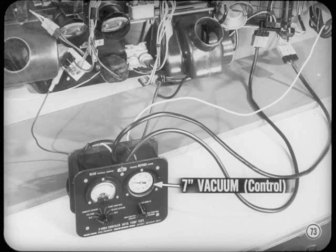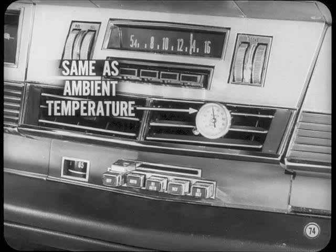Disconnect the wires from the compressor clutch and run the engine at curb idle speed. Place a thermometer in the right center air conditioning outlet, push the auto button, and set the tester vacuum dial so the tester vacuum gauge reads 7 inches. This is the control vacuum supply to the water valve thermostat. When the thermometer in the outlet settles down, it should read the same as the ambient temperature outside the car. Remember, the compressor is disconnected and the water valve should be closed.